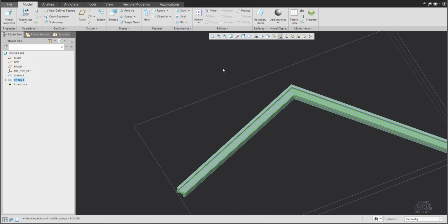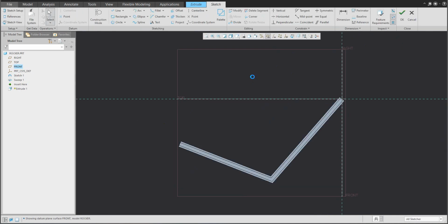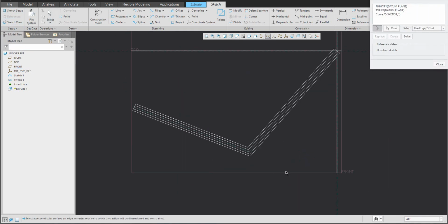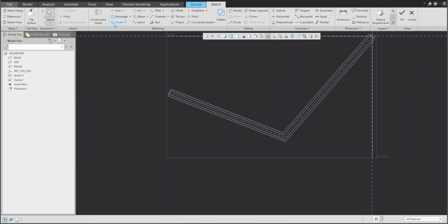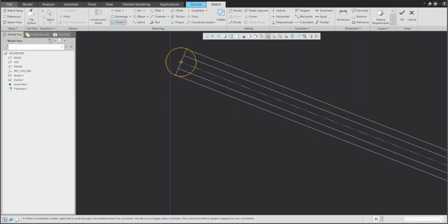What is really great is that over here is the sketch, so we can use this sketch a couple of times, so you know that we need to create a couple of points where we would like to connect the wheels and pin connection and so on. So I will change the visualization, and as the reference I will select my sketch directly here, and with a really easy function create a circle.